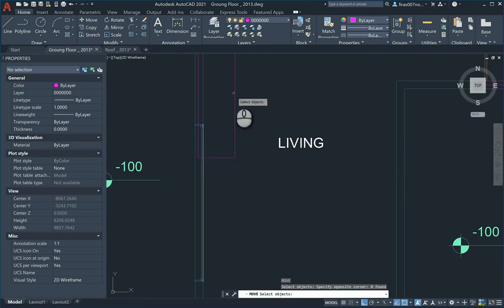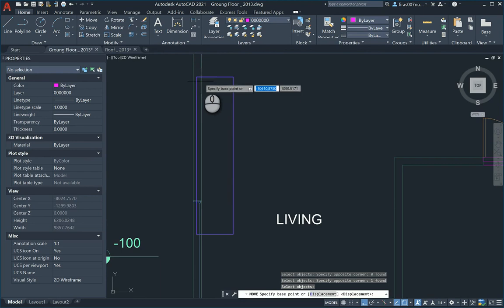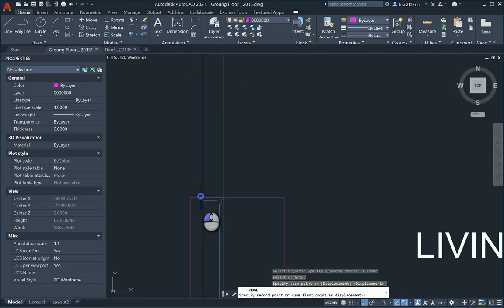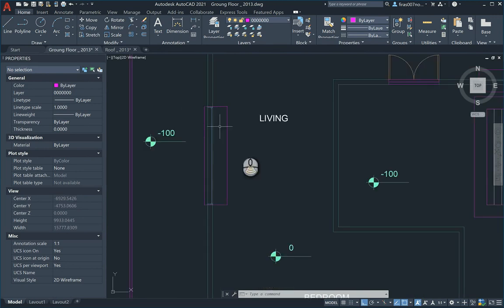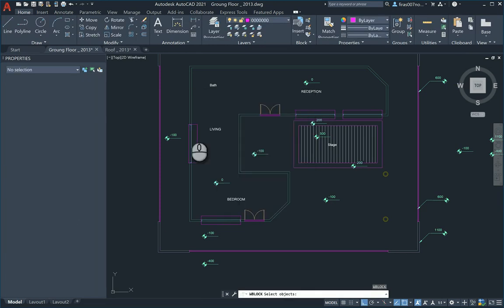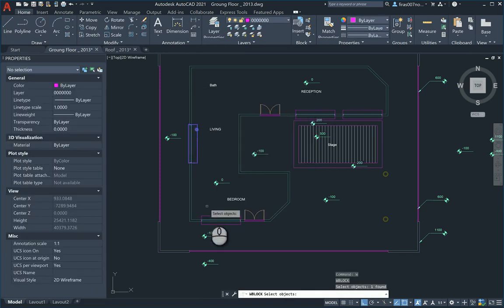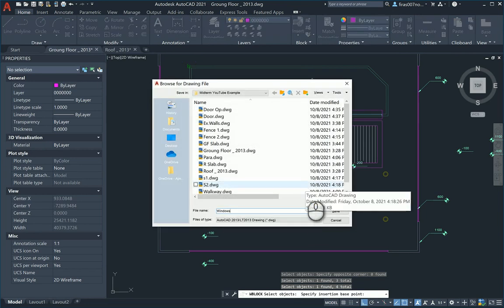Okay, make sure that when you place the cutting geometry, this edge and this edge are bigger than the edges of the wall. Now go ahead, right, block, and let's just cut. Actually, let's select those cutting windows, and I will name them windows opening.